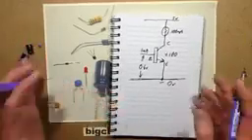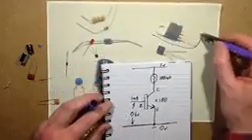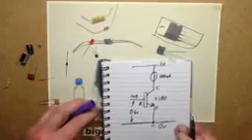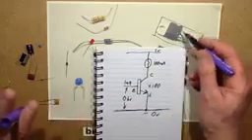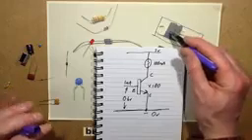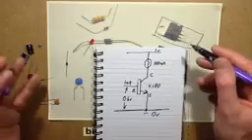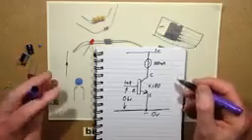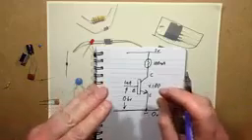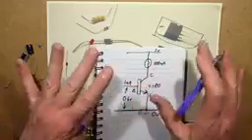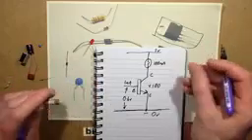Other types of transistors are things like this one pictured here, a MOSFET, and they're optimized for switching really high loads. I chose the STP36NF06L for my RGB controllers because one of the nicest things about it is that it can handle a lot of current, and its on-state resistance is so low that it doesn't impede the flow of current when it's turned on, so it doesn't really get very warm.